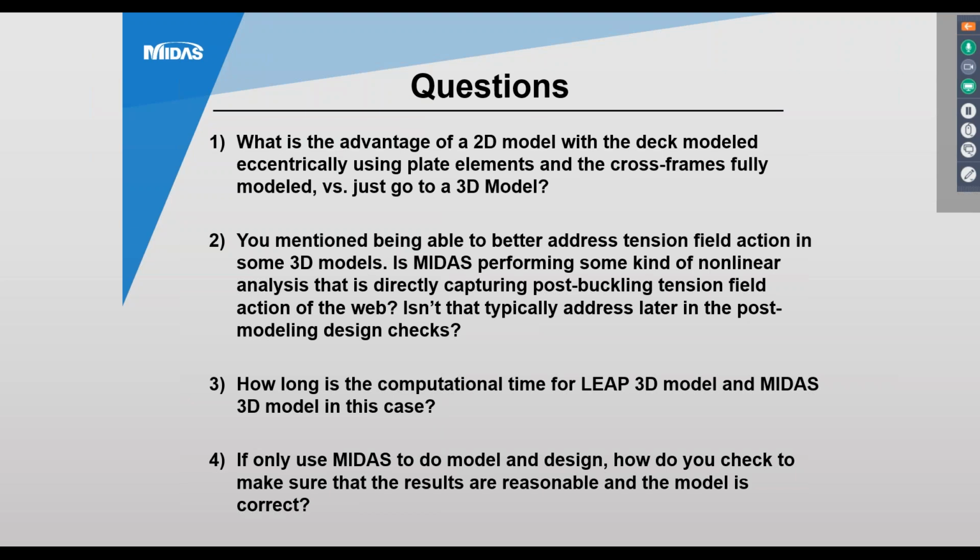And how long is the computational time for LEAP 3D and Midas 3D? So the LEAP full 3D, we were not actually able to get to function. There was an issue in the program. They have since released a patch, and I have not actually gone and tried to have it create the 3D model as yet. But there were issues where it was not creating the supports as it should have been, and it was crashing. So I can only talk to the LEAP Grillage.